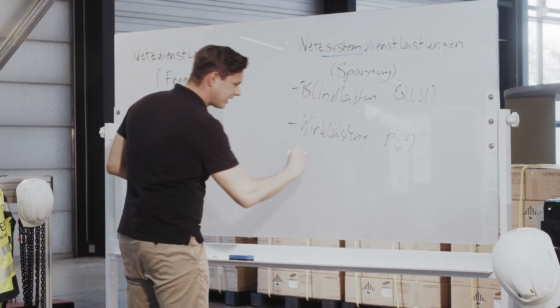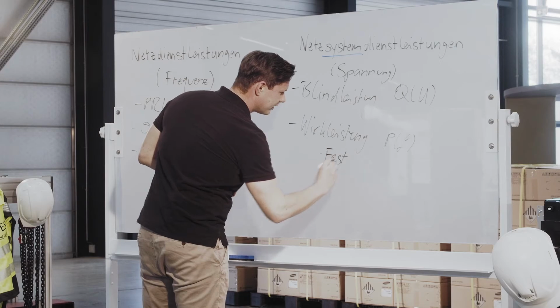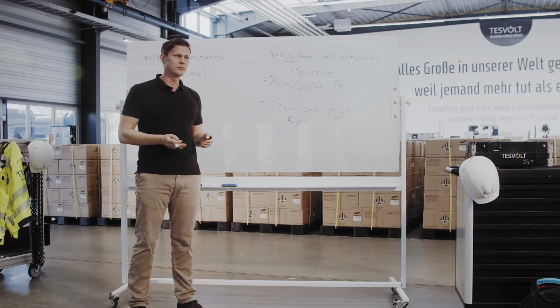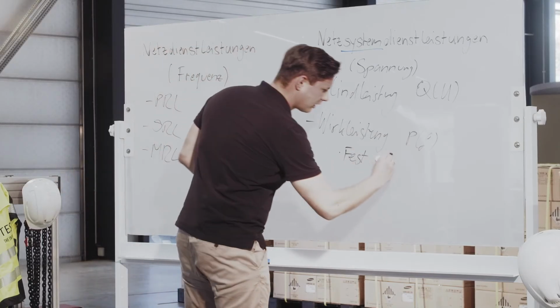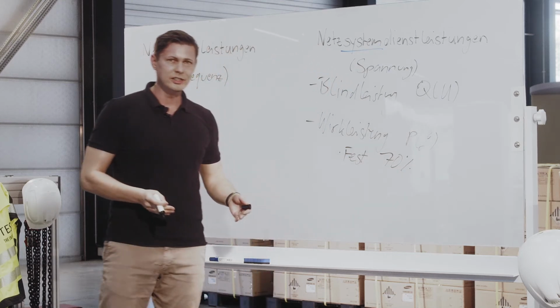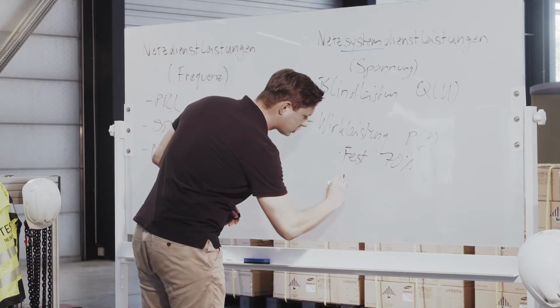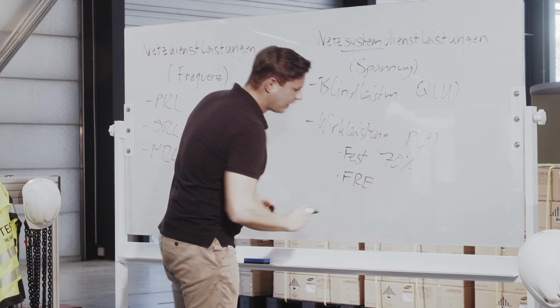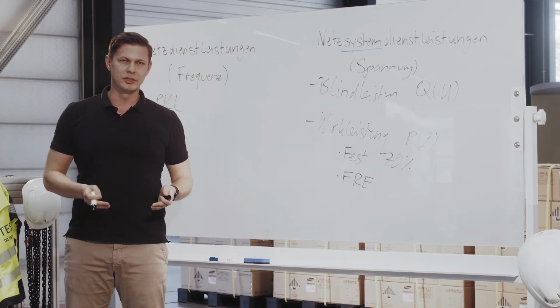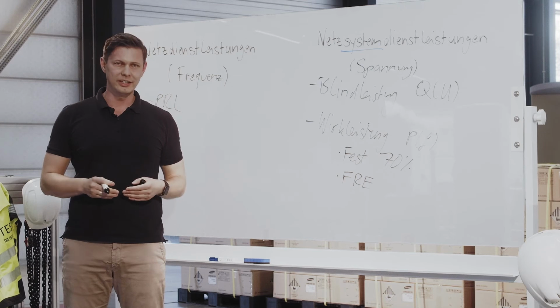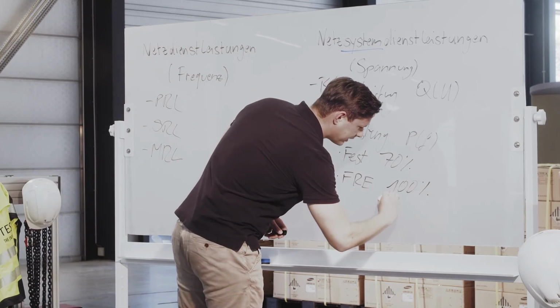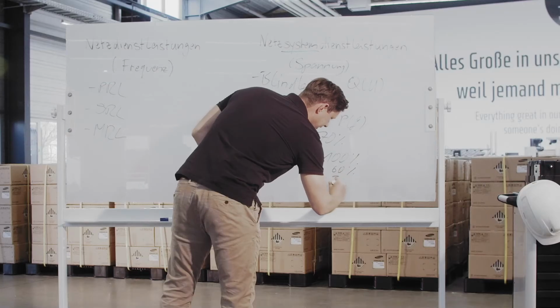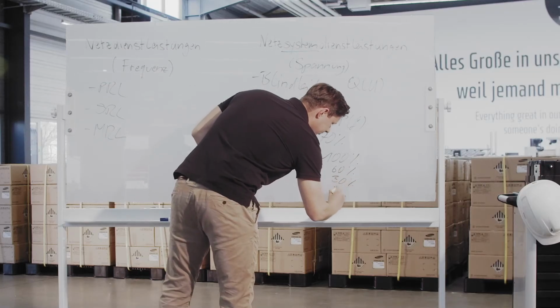There are 2 methods for this. One is the fixed setting of the active power limitation of my generating plants. For generation plants smaller than 30 kilowatts, we have the 70% rule, for example. This is a rigid setting. The second method is a dynamic setting via a ripple control receiver. The energy supplier can control the system remotely and in various modes by way of the ripple control receiver. Conventional wisdom is to regulate active power by 100%, 60%, 30%, and so that I have no power available at all.